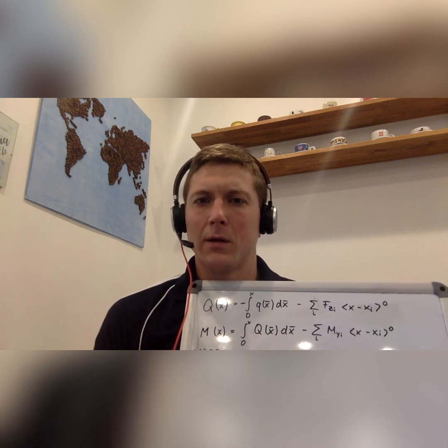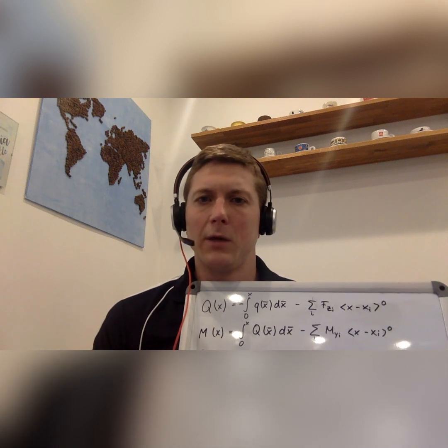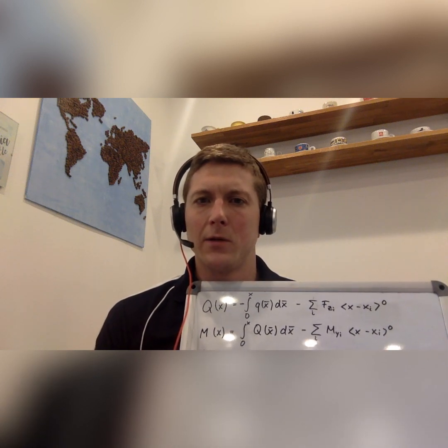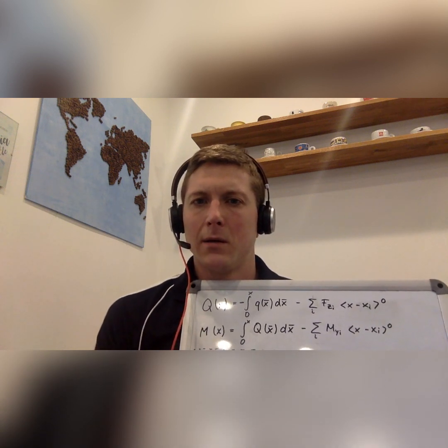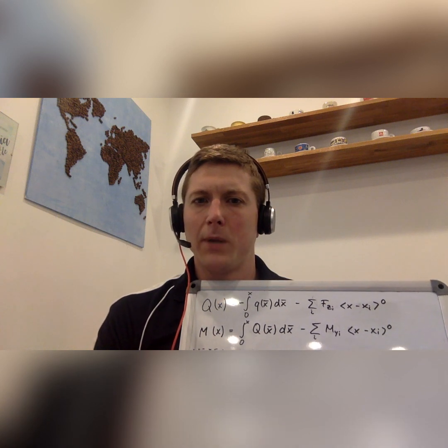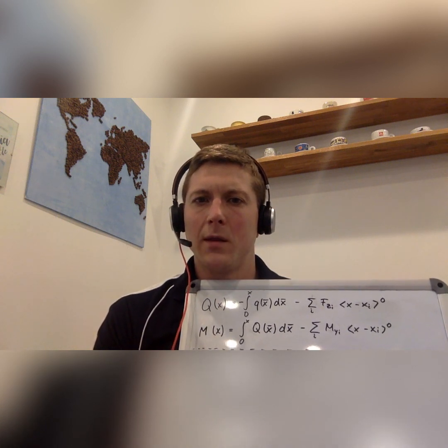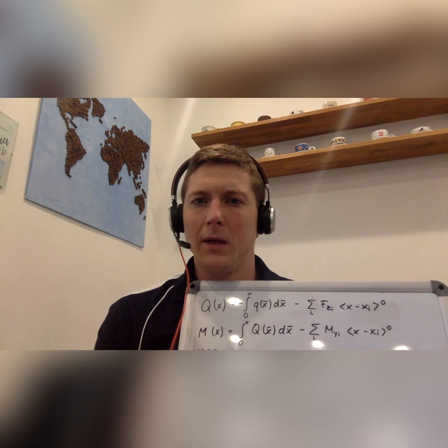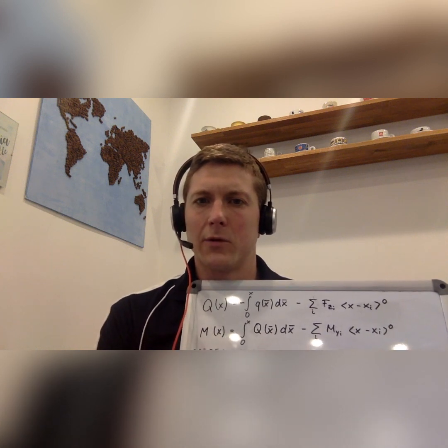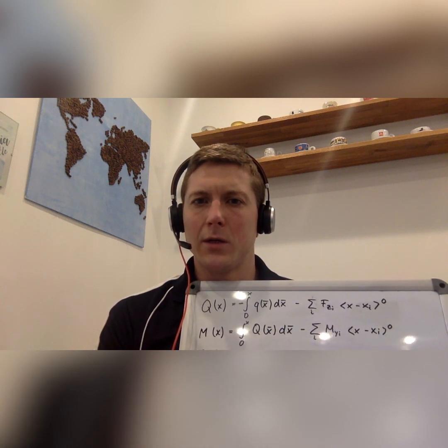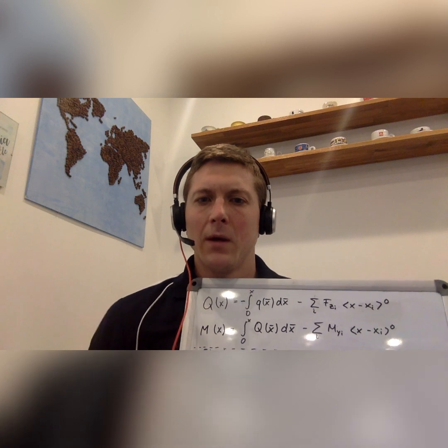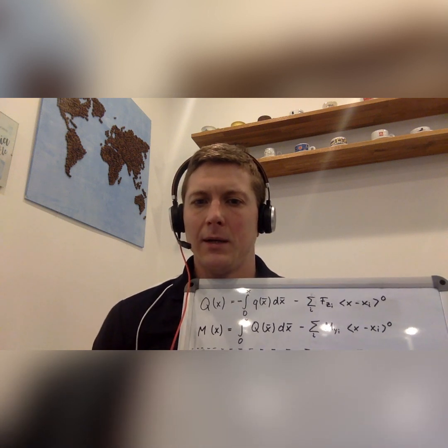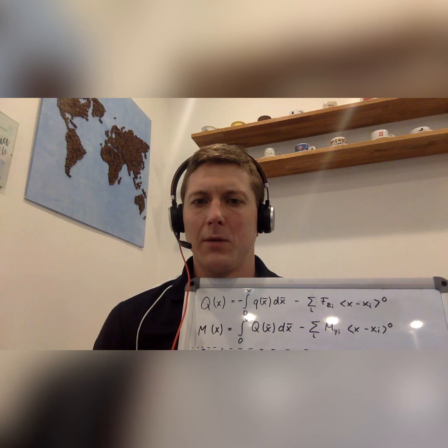It's similar to, keep in mind, the first topic we had in mechanics of materials, where we had the tensile bar. There you could say that if you apply a force, you get some elongation in your bar, and if your system has more bearing reactions, so more unknowns, than equilibrium conditions you could set up out of the statics, then there is maybe a link between the deformations and the forces which are acting there, and you could set up additional equations to solve for all the unknowns. And for the bearing of beams, it's more or less identical to the tensile bars.